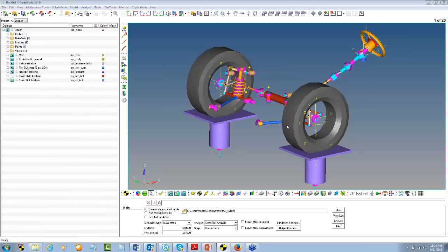What is the optimum roll angle? Well, that you need to answer while you are designing the vehicle. What is the stiffness of the spring, the stiffness of the tire, and that would govern what roll angle you are going to get. Whatever roll angle you get in the worst case scenario, and the worst case scenario would be the tire limits, right? So you can find what roll angle the vehicle is going to experience, and you pick that roll angle value and put it over here.